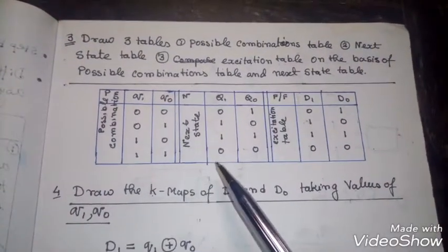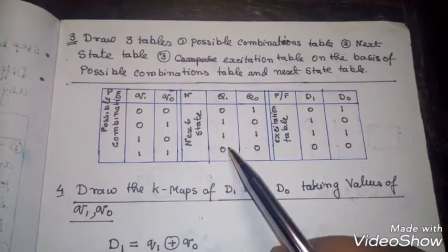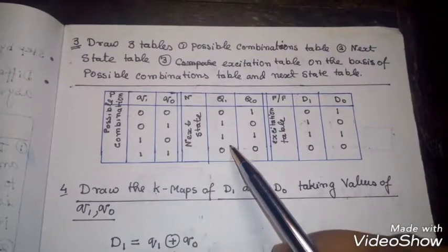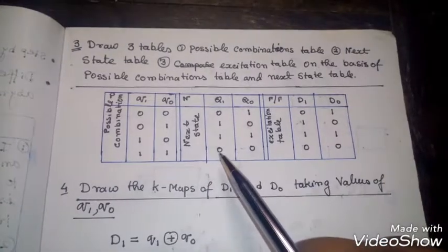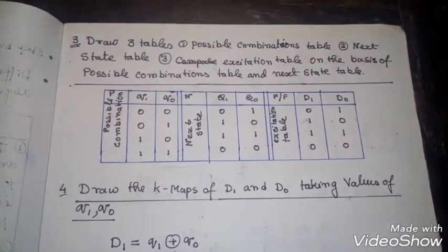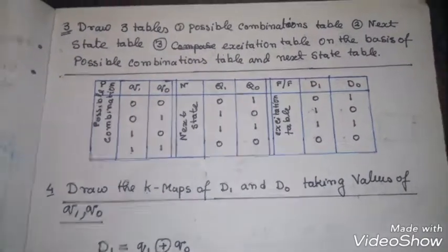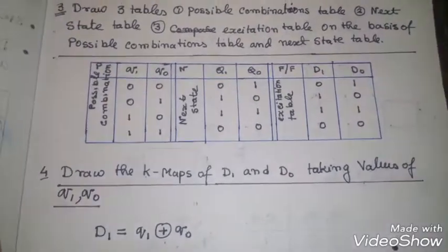Now if it was not a ring counter, then I wouldn't need anything after 3. At that time my next state after 3, that is 11, would become don't care, don't care. We have to mark those with don't care symbols. So after completing this table, I have to